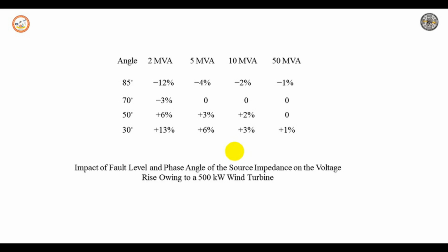A stochastic approach is used in the study, as a deterministic approach would have resulted in a hosting capacity equal to 65 kilowatts. The calculated voltage rise at the maximum production is 2.2% and 2.9% respectively in this example only. Measurement on a 110 kilowatt site, however, shows an increase in the maximum voltage of only 1.5%.